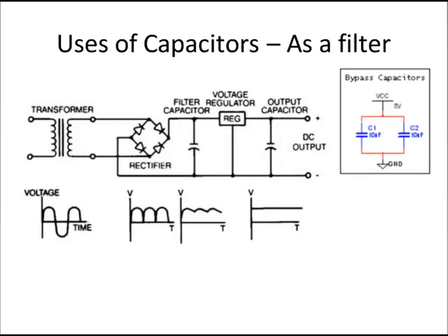We have on the left-hand side the voltage in time, and you can see that's an alternating sinusoidal, just like we saw in MET 8100. It goes through something called a rectifier, which has some diodes in it, and it half-wave rectifies the signal so that we only get the positive sides of this sinusoidal, and then it goes through a filter capacitor, and you can see that the waveform is starting to be smoothed out, but it needs a little bit more help.